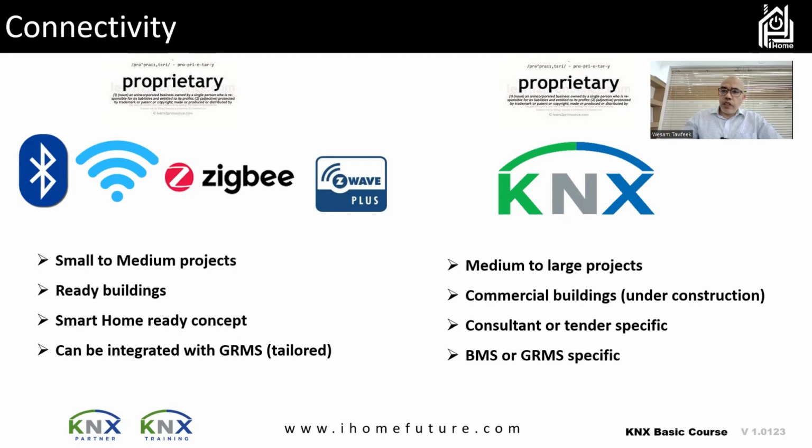However, if you have a place, let's say a villa, an office, a house, which is furnished or ready to move in, so you don't still have the time to put the cables for KNX or to review the electric cables, then KNX would be hard to implement because you need to do a lot of changes in the interior of the house. In this way, I recommend that you can go with something wireless. I always recommend, if you're going wireless, to go with Z-Wave. Okay. Both Z-Wave and KNX are open protocols, so they have a lot of companies working with them.